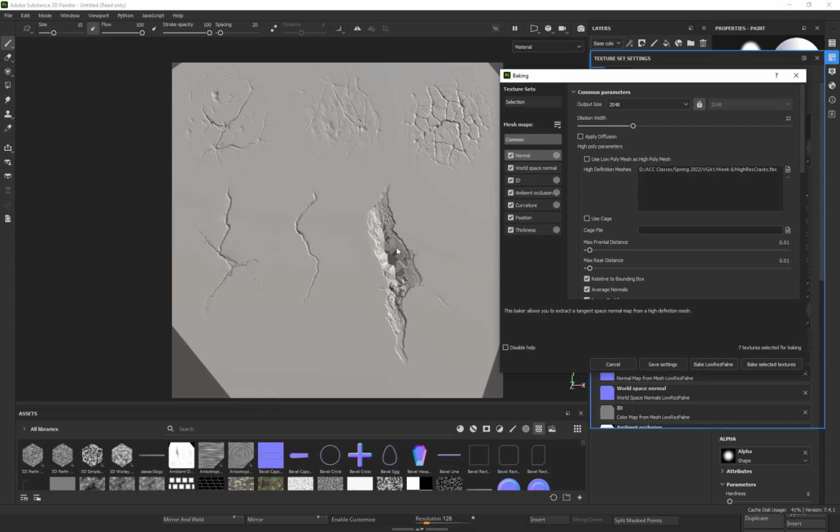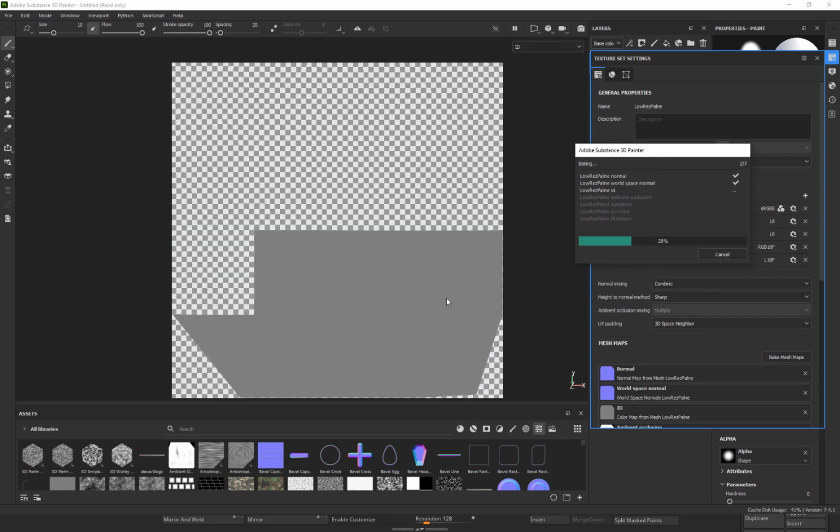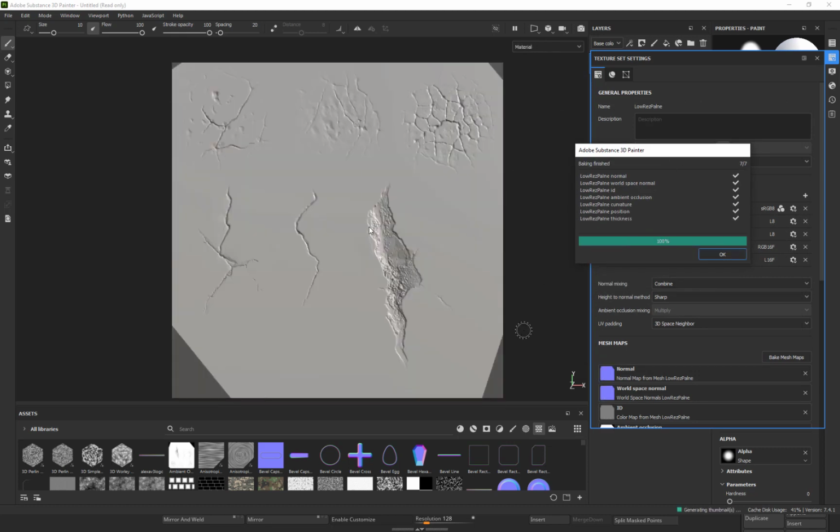Now, this problem is not from extruding out, like most normals are usually outward based. This is because it doesn't go deep enough backwards, and those are both set to right here. If you picture a cage, this is like a cage that only goes so far out and so far in, and really you don't want to go too high, because if you go too high then it distorts the line, it tries to push past it and weird stuff. But I just say 0.05 instead of 0.01, and I bake it. Move this out of the way. Bam, it's fixed.